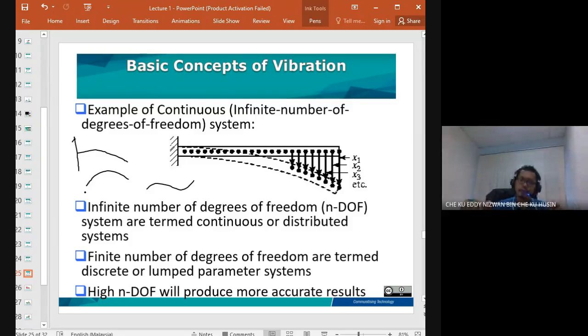The same goes for the Tacoma bridge, if you can still refresh your memory. You can see that the bridge is twisting, right? It is due to the twisting mode at a certain frequency, which is the resonant frequency induced by vortex shedding from the wind. The frequency of vortex shedding is equivalent to the twisting mode. That's why you can see the bridge twisting. So that's the relationship.